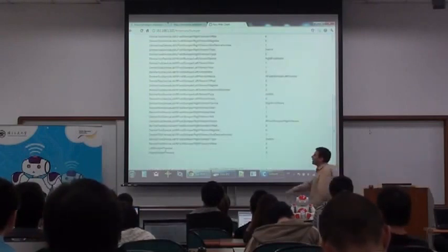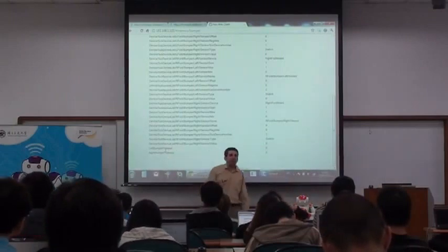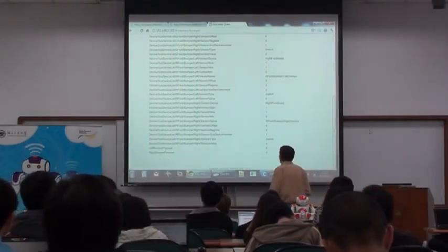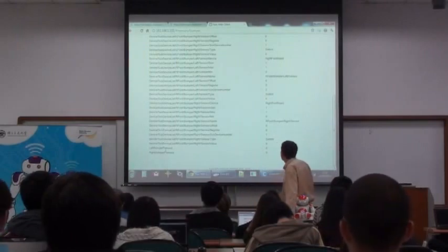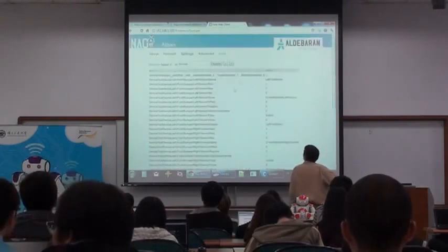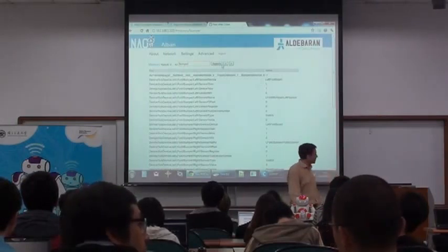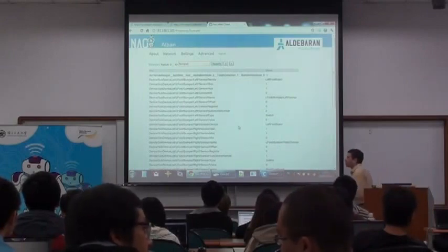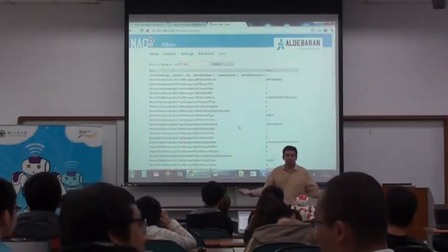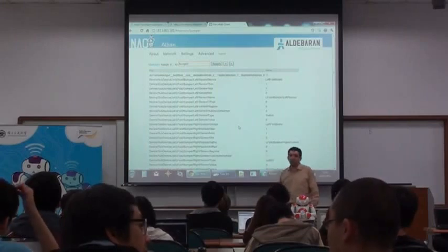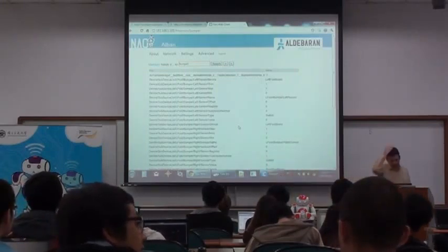Left bumper press. These two values, when you press this, they are changed in ALMemory. Of course, here it's a static web page, so if I press it, nothing happens unless I update again. But do that, and you'll see the value change. So yes, this one is quite useful. You can store your own data. You can give any name. So if you make a behavior that stores some data, if you want to debug it, you can quickly go to the web page and see the status.